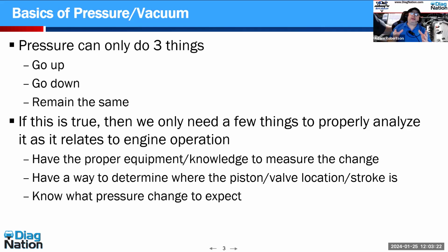I have to agree that in some cases that works well. For example, if you're trying to look at cam-crank synchronization, that sort of thing is great to compare known good to ours. However, when it comes to many other waveforms, and a little bit beyond the scope, pardon the pun, of this class, there are a lot of hiccups in that way of learning lab scopes. But I can tell you from our topic today, with the basics of pressure and vacuum, or if you just want to say pressure, because really that's all it is, it really needs to be understood that comparing known good to yours really isn't going to work.